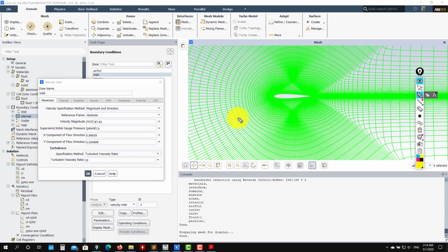Okay, so basically, if your flow is coming in this direction, the lift and drag forces are, lift is perpendicular and drag is parallel to this one. So you will need to rotate how the forces are computed. Very important. Do not forget that, because I see people consistently make this error. Okay, so you set up these quantities, velocity magnitude, the flow direction,